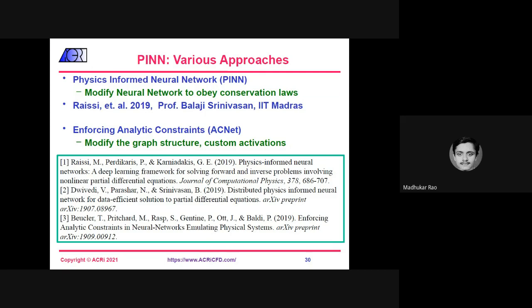We know that physically there are certain constraints to be imposed on the solution too. For example, your temperature should always be positive. Negative absolute temperature is basically a junk result, right? Likewise, negative values of your turbulent kinetic energy or species concentration are also physically wrong and could damage the complete solution.